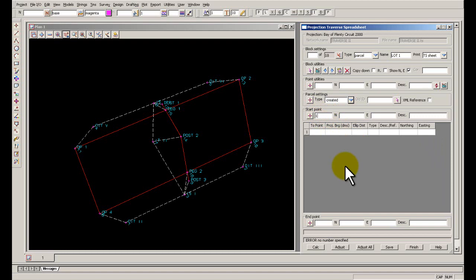So I'm going to start from 15, like so, and so this is a pass 15 to 13, like so, and then through to 10. I've got that as CA. Sometimes you might want to put them as B boundaries or things like that for loading them or getting the XML right, but at this stage here it's probably fine. Through to 16. I'm just treating these as calculations rather than as an input exercise into Land Online. 16, yeah, it all seems to be good.